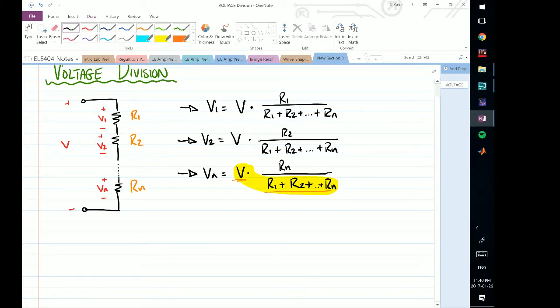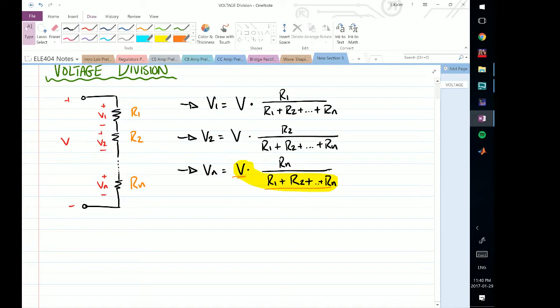And so we can generalize the voltage division as the multiplication of the terminals. So my terminal voltage here, or my voltage across the entire branch, I should say, is V. Now notice this is not a source, so this applies for any branch. This can be any branch that is a sub-circuit or a subsection of a larger circuit, and I can still divide the voltage so long as I know what this voltage is between one point and the next.